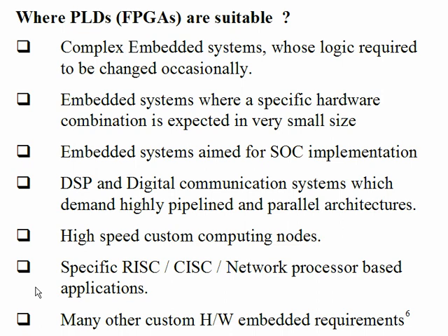Got the point? I think most of you studied 8085, 8086, this kind of processor. There you have studied these words, if you remember: instruction cycle, machine cycle, T cycle. The instruction cycle is the time taken by one instruction for its execution. Not only time taken, we also talk about the amount of job done for executing one instruction. So one instruction cycle has several machine cycles, and each machine cycle has several T cycles.